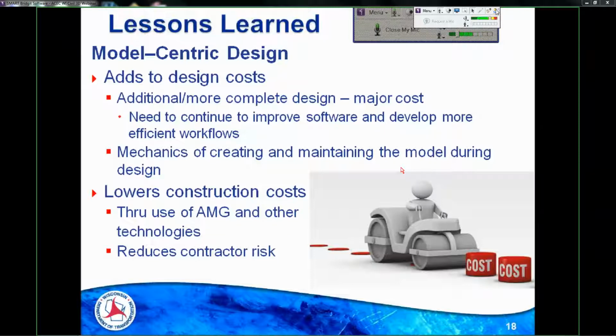They're producing models at 1 foot frequencies, okay? And when we give them surfaces, they can't add that detail to the surface. But when we give them longitudinal break lines, they have tools that'll take into consideration vertical curvature of profiles, horizontal curvature of alignments, horizontal curvature of target objects, and it will chord out those individual line segments.